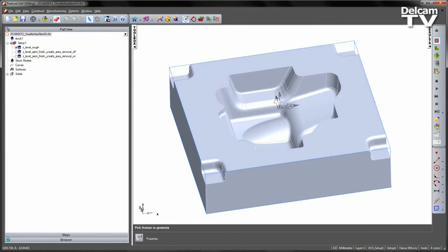As with Z-level roughing, unsafe area removal can be used in finishing. This option removes small toolpath segments to prevent tool damage when using non-center cutting tools. When machining down into small pockets, removing these small segments stops the central non-cutting underside of the tool from hitting the material. This option filters out the machining of confined areas where there is limited movement of the cutting tool